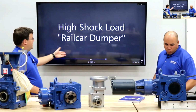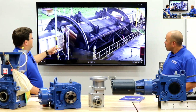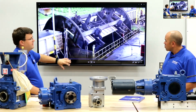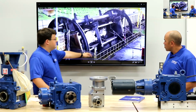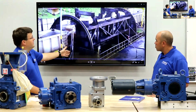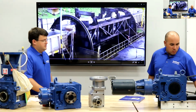And then high shock, you've seen this one already, this railcar dumper. So it's not shock yet, but as soon as that dumps, that whole car is moving around and bouncing back. And that's a high, heavy load that's shocking back into the system. And same thing, as I mentioned below, all that coal is dumping on that conveyor. So that gearbox has to be prepared for that shock load as well, because that's a massive amount of weight dumping down onto that conveyor. So that would definitely be a high shock application.